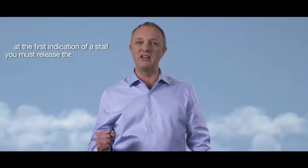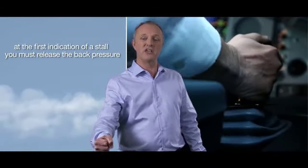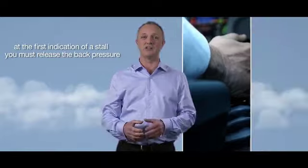In this film, you have seen various theoretical and practical aspects of stall situations. The most important thing to remember is that at the first indication of a stall, you must release the back pressure and, if necessary, push the stick forward to decrease the angle of attack until the stall indications are no longer present. Remember, it is always better to avoid a stall, but should you encounter one, strictly apply the recovery procedures published in your aircraft operations manual.